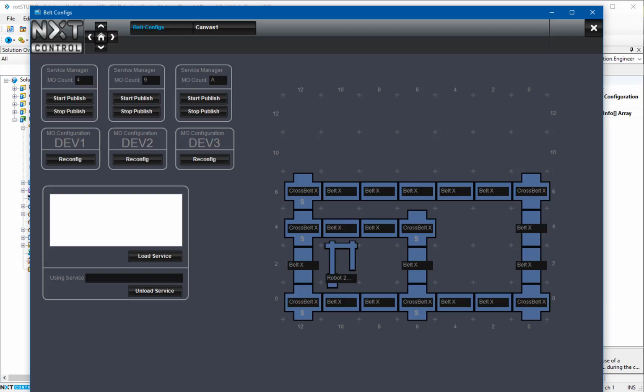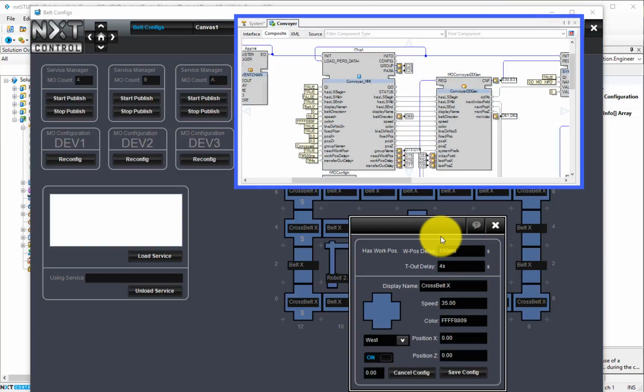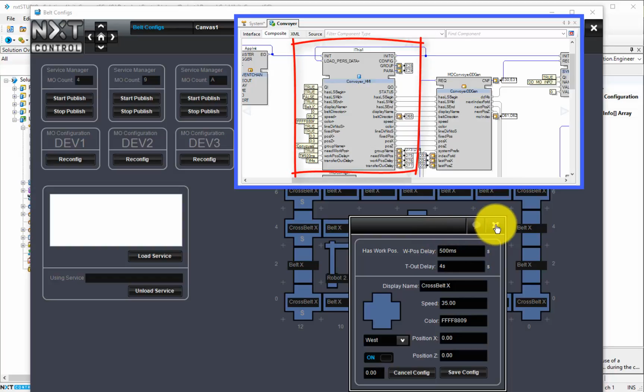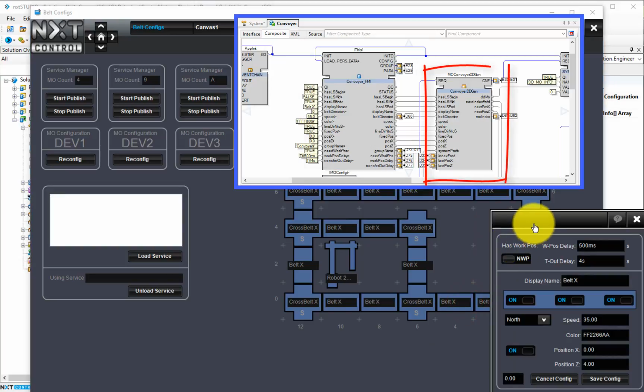Let's have a look at the available settings which can be modified from the HMI, which directly modify the self-description information of an object. The values are set through the HMI interface and used by the device description generator to build the self-description information.